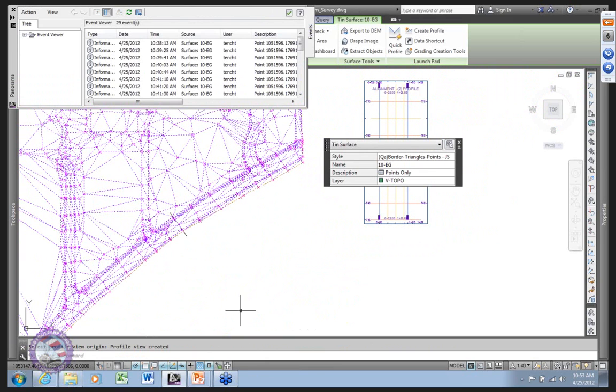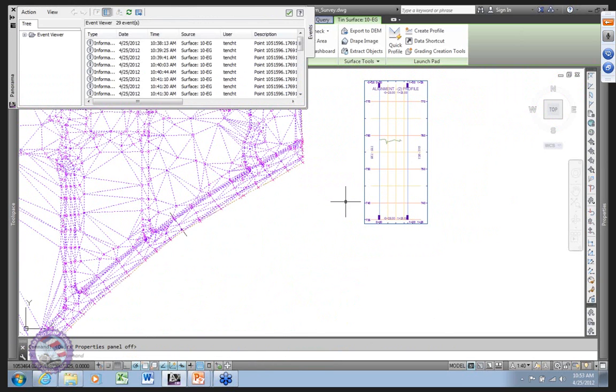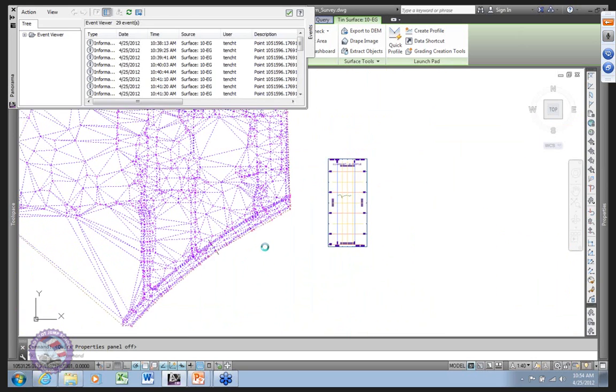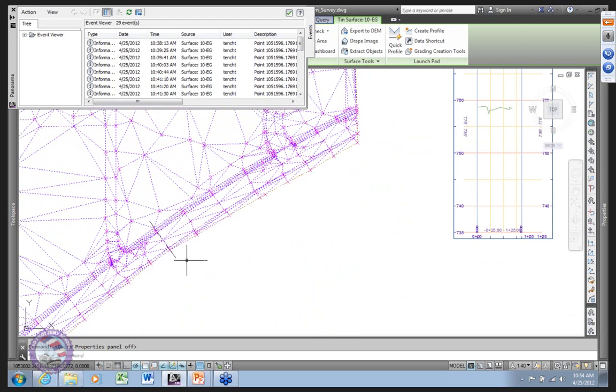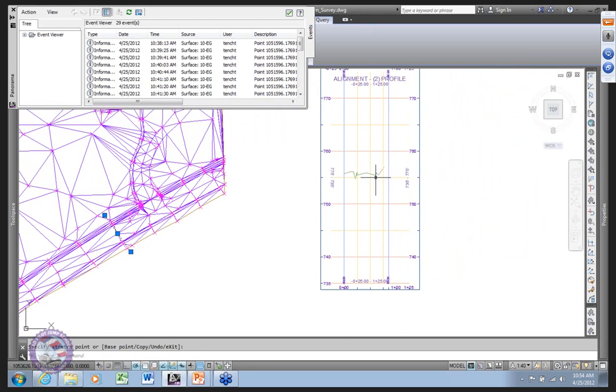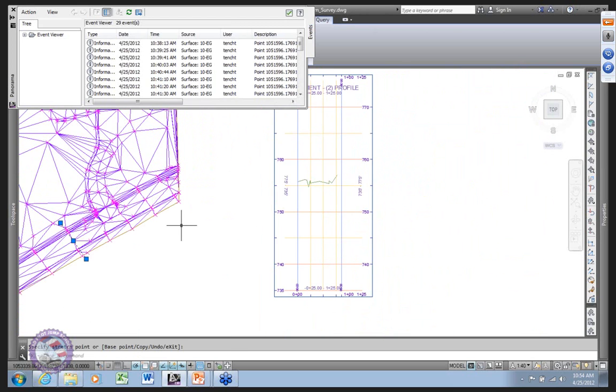Okay, and I'm going to turn off my Q mode box just so that's not annoying us. And we can see we sort of got a thing that looks like a road. We only shot back of curb, so we're kind of going from a flow line shot, I think, here, right, to a back of curb shot. Okay, but we got a surface that looks like a real world surface. We already pointed out, oh, hey, we can also move this guy around. We can move it to that station shot, right? Okay, it will update dynamically, right, because they're connected together.